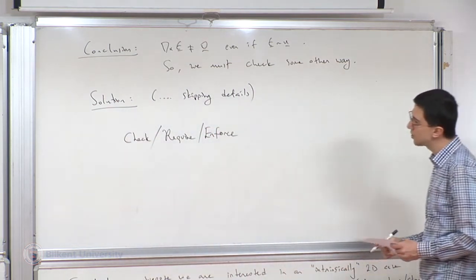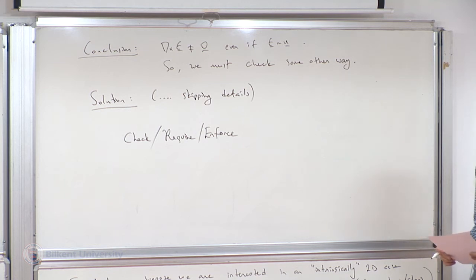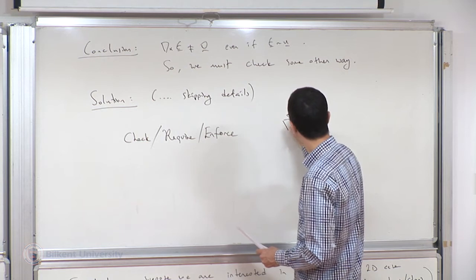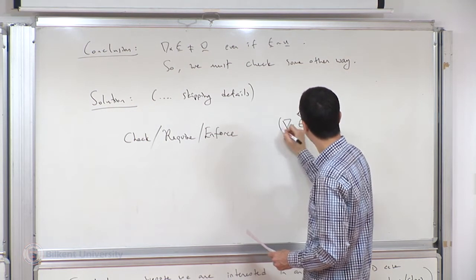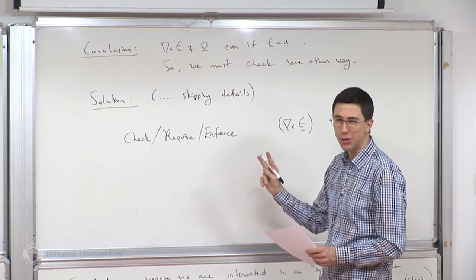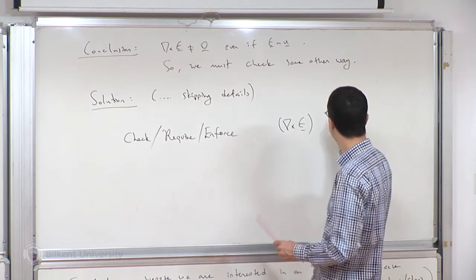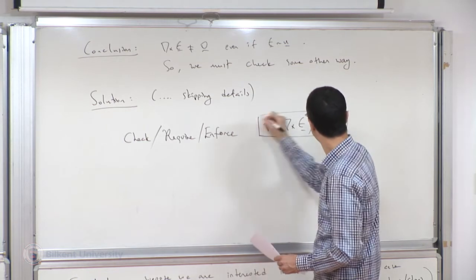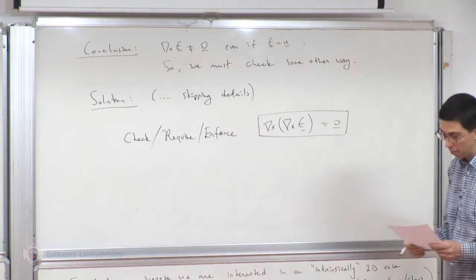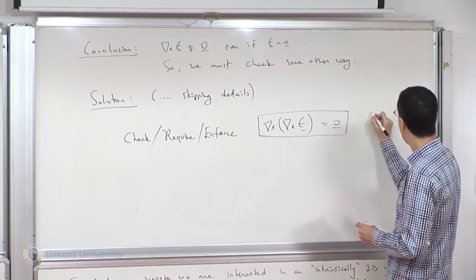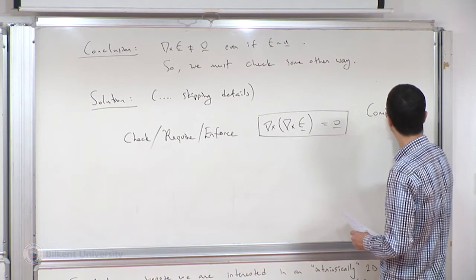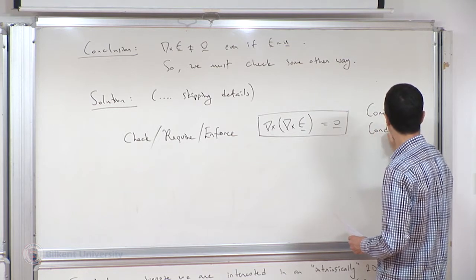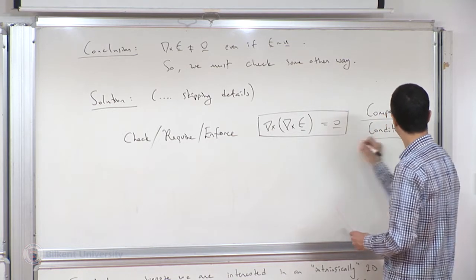So in any case, to check the compatibility of the strain field with the existence of a U, we want to check not only a single curl of epsilon, but two curls. If you take two curls and if it's equal to 0, then epsilon is compatible. And these are eventually called the compatibility conditions.